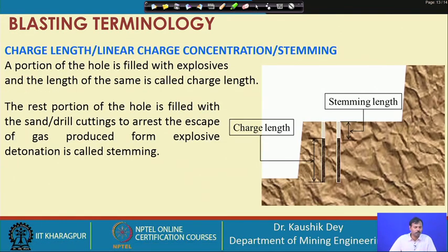So, the next terminology we should know is the charge length or linear charge concentration. As we have carried out the drilling, you can see that up to a certain length inside the drill hole we have inserted the explosive and the rest part we left. This explosive which is inserted into the drill hole, that length is called charge length. What will happen to the remaining portion of the hole? In the remaining portion of the hole, we insert some sandy material or some plugging system